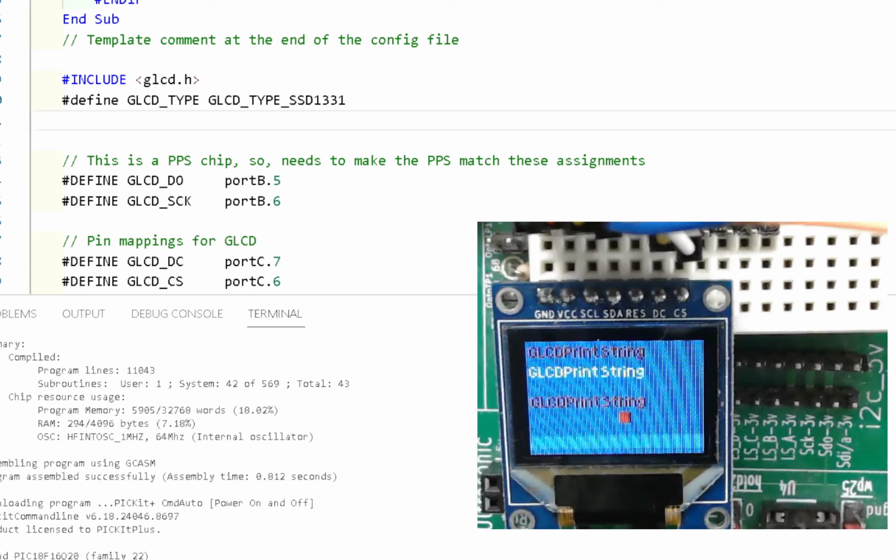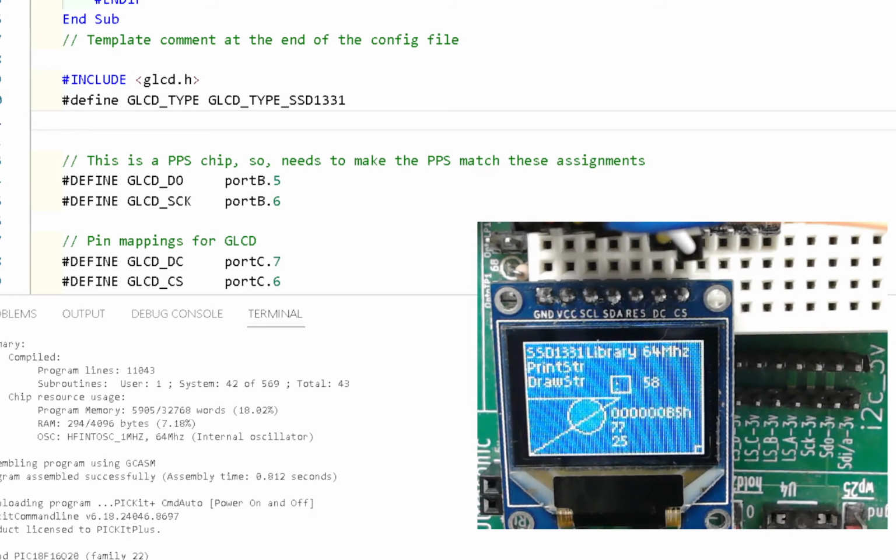And here we go, it's going through the same process of blue screen, red screen, and then it will end up in that demonstration. And you'll see that the numbers are slightly faster because there are fewer instructions to send the data out when using Hardware SPI. It's a deeper library, there's more stack used in the library, but it's fewer instructions overall. Therefore, it is faster. And that just proves how fast it is. You can see it visually.